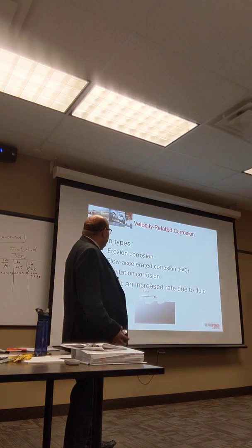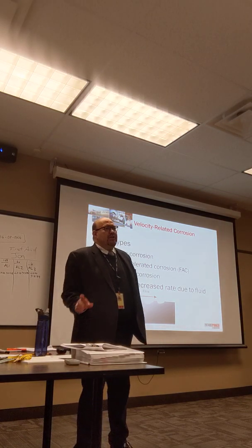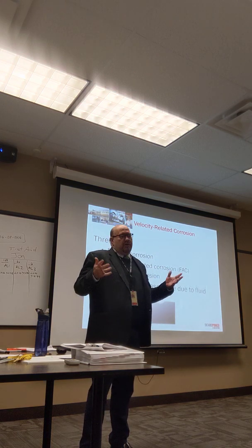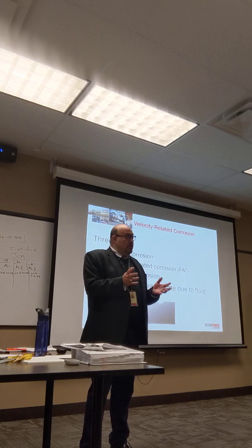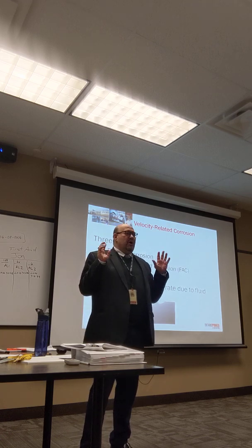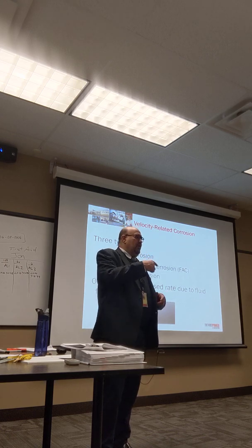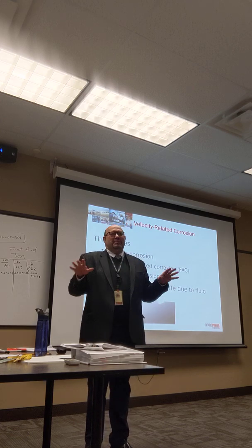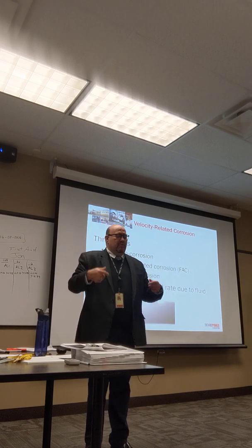Velocity-related corrosion. So, of course, this is FAC. And velocity-related corrosion is actually, we suffer from it at OPG. We experience flow accelerated corrosion. Now, fortunately, knock on wood, we never had a major problem like they had at Mihama in Japan. But when you look at the root cause of what happened, they never maintained that pipe. They never even inspected that pipe that actually ruptured.